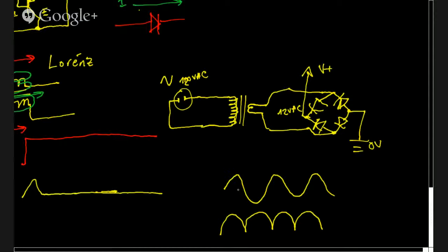And we can use capacitors. We normally put some capacitance in there. So now we have our capacitor charging, and the capacitor smooths it out. We'd end up with something closer to this, because the capacitor charges, holds the charge and starts to discharge, and then the positive half cycle replenishes it, and you get a bit of a ripple.